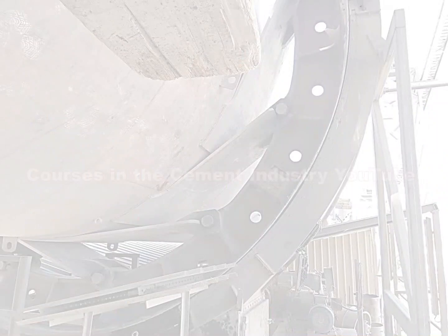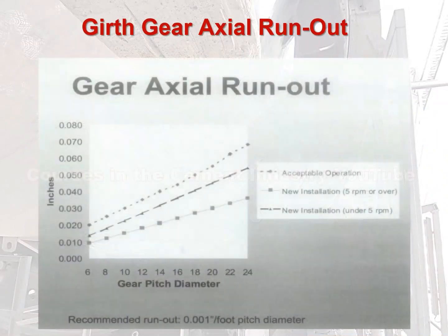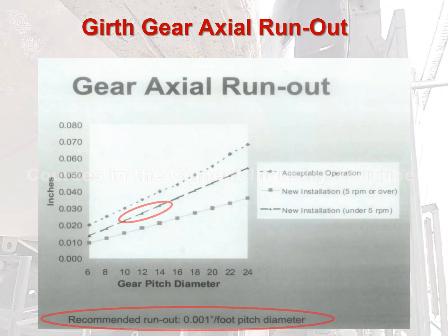Girth gear axial runout. In this picture, recommended runout, 0.001 inch per foot of pitch diameter.